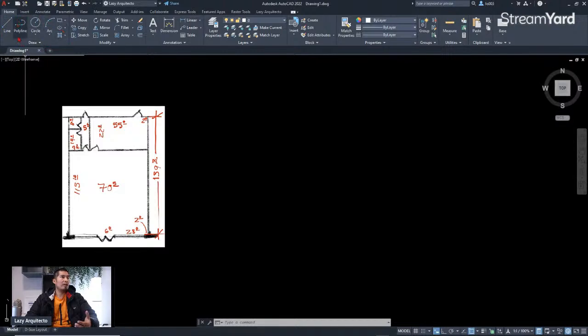This is called a panel, and it's on the Home tab. These are called tabs. So if I want to draw, I know I can go to the Draw panel. If I already have a drawing here and I need to edit or modify things, I can go to the Modify panel. So I can copy objects, scale, rotate objects, and so on. Again, all of the tools are organized here.